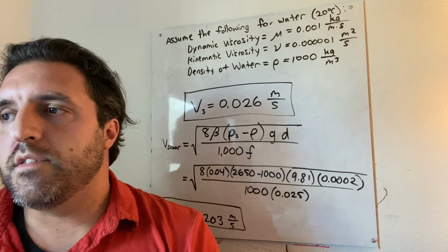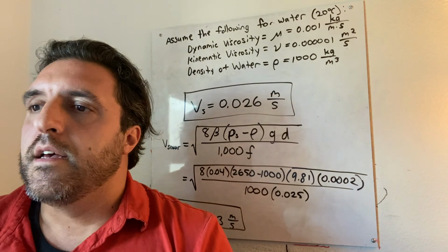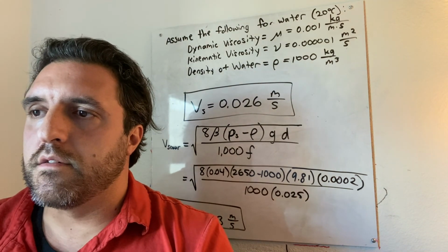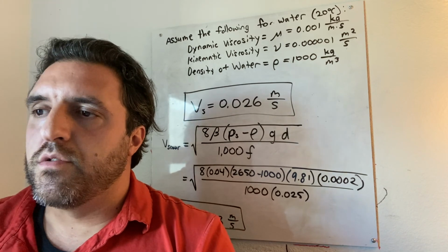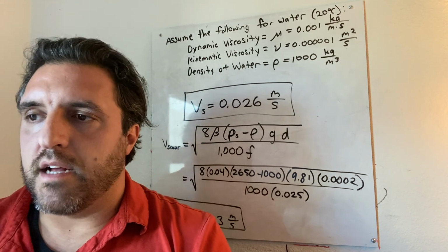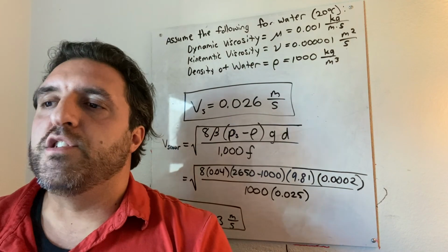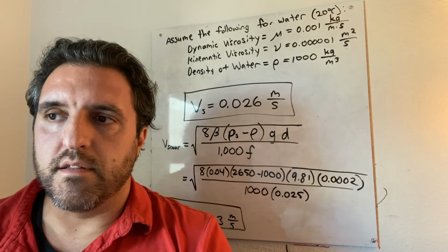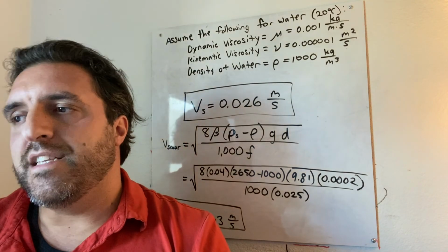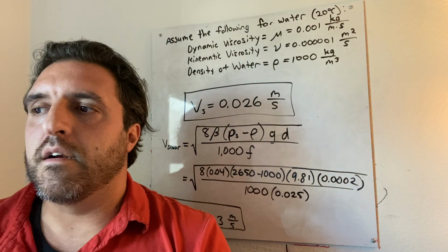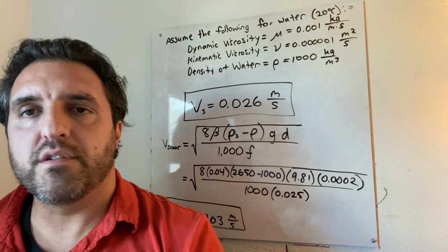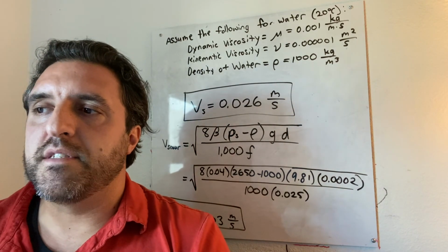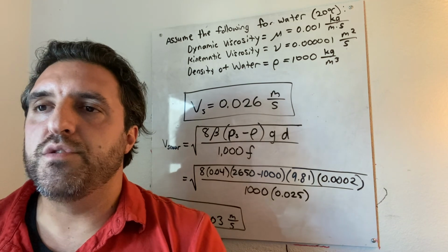And the answer, I would say, given the fact that the majority of grit particles in most wastewater systems, based on the plots you see here, have a size that's a little bit less than 200 microns. And in addition, for those particles that are 100 to 200 microns, the majority tend to have specific gravities that are much lower than 2.65.